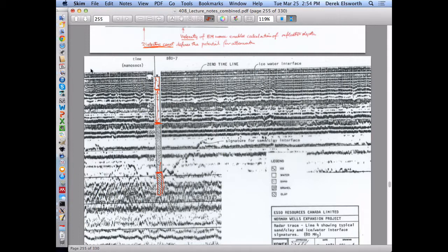So now across the top of this surface, you drive a GPR unit, and you use this GPR unit to get this profile. This other kind of messy profile is what a GPR profile looks like. The idea is that you have a transmitter and a receiver, and it measures the time of flight that it takes to go down and come back up. It takes this time of flight and plots it as a trace.